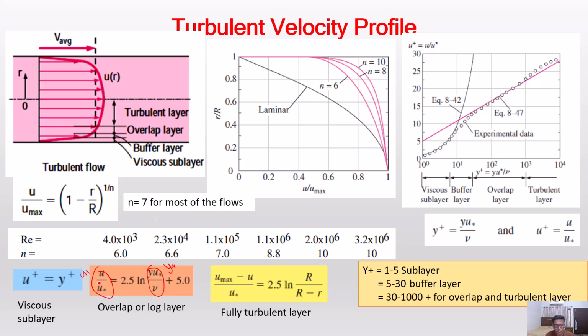So to solve this through CFD, this is implemented in the software. We don't need to select it ourselves. So if you are solving with the wall function, then this equation will be activated, and if you are solving with y plus equal to or less than 1, then this equation will be implemented. So how is this implemented? Actually, this is the mesh.